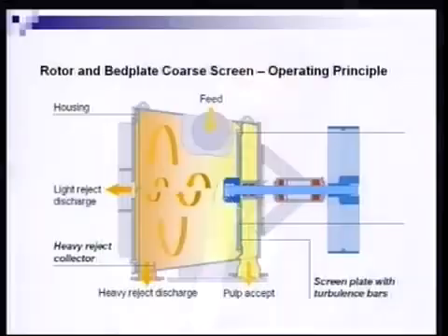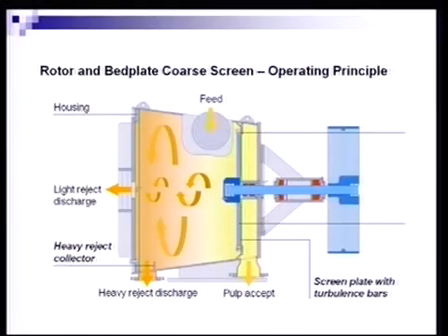The end of the pressure vessel here is flared out in order to promote the circulation that happens inside the secondary screen, and it has a heavy outlet discharge. It keeps the heavy material away from the rotor, which gives you longer rotor life, and provides another method for sand removal, staple removal, and heavy debris removal in the secondary coarse screen.